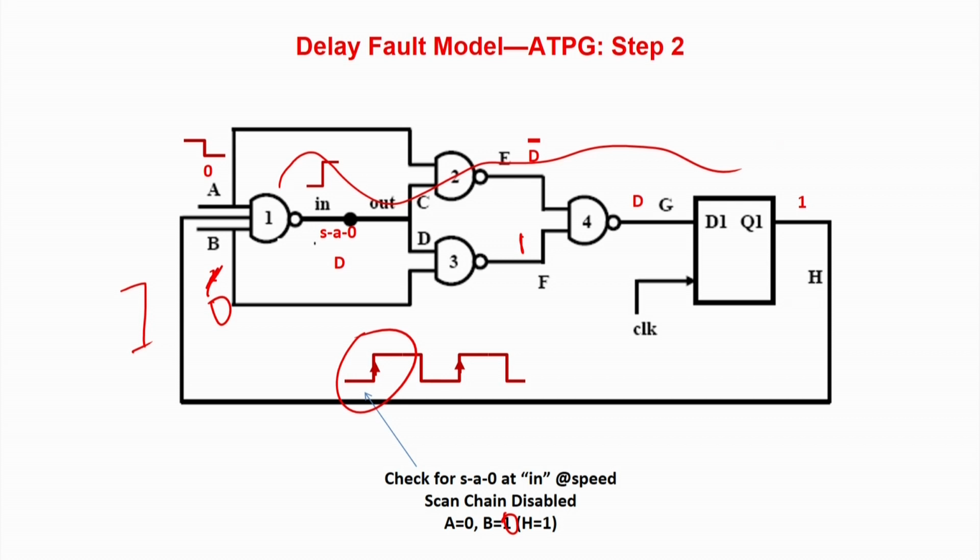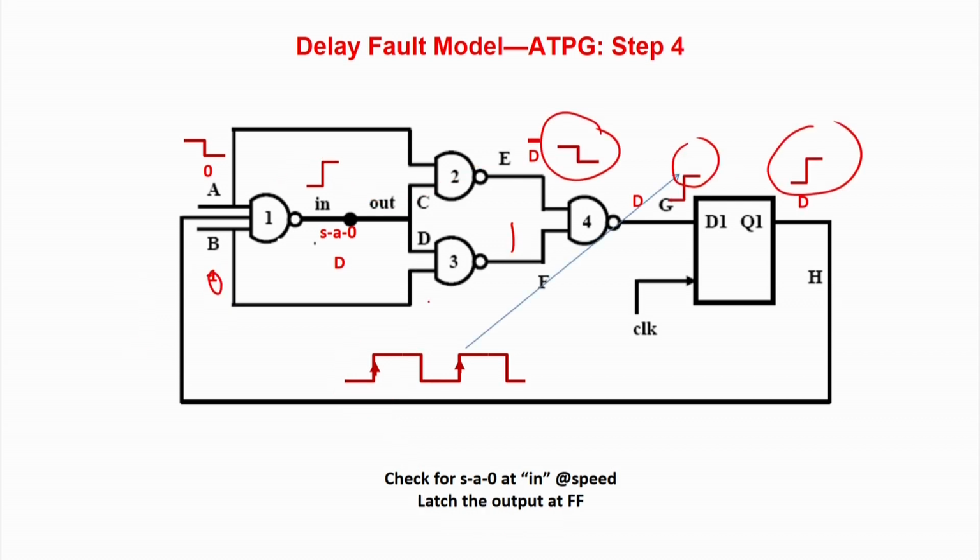So this line is just for justification, and the lines A, in, out, E and G are for propagation and sensitization, so that I get a 0 over here and the value is a 1 over here. So in this case, this rise should happen before the arrival, and this is the duration. This change should happen just after this, because this point is triggering it. I am sorry, I should say that this is actually the trigger point.